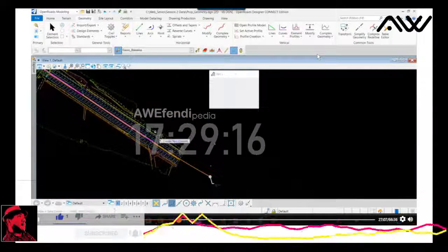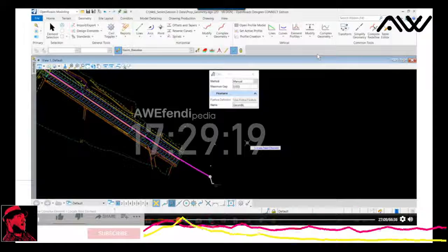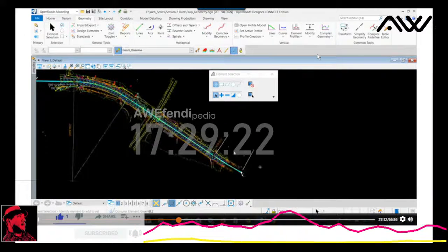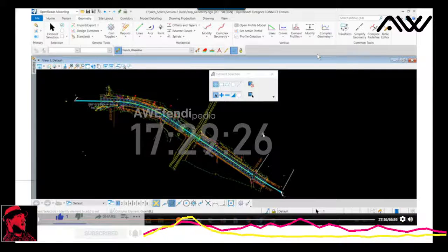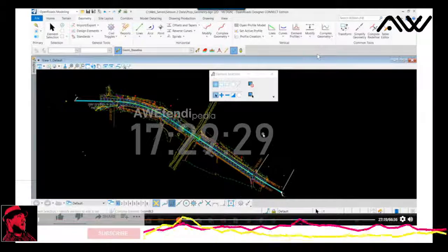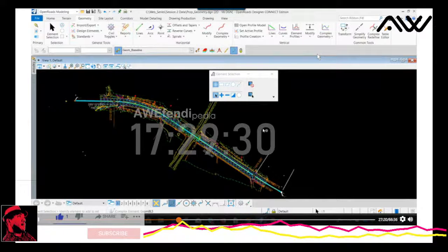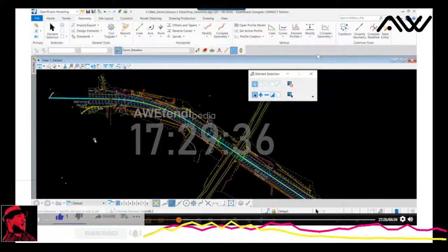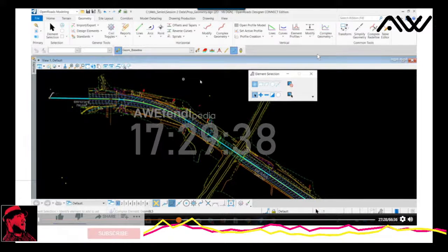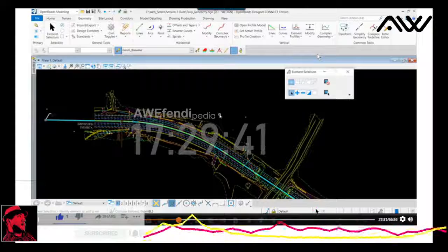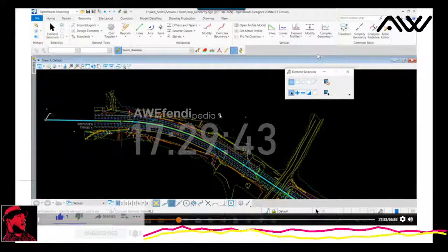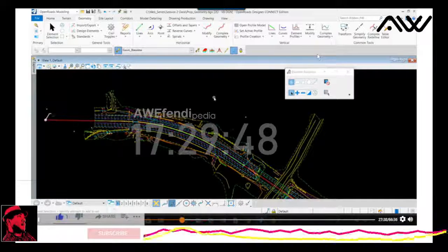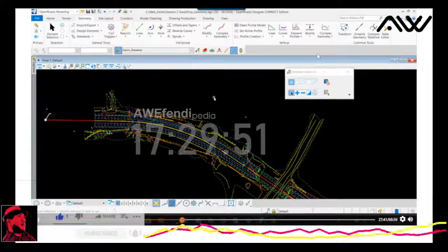And click through there and data point, and now we have our center line created. Okay, so we have now created that baseline, that horizontal element. And we did that again using a graphical elemental method. This is not the only way I could have created this. I could have created it in different ways graphically, and that would have been okay. So this way I adhered to what we knew to be existing and then drew that in graphically.